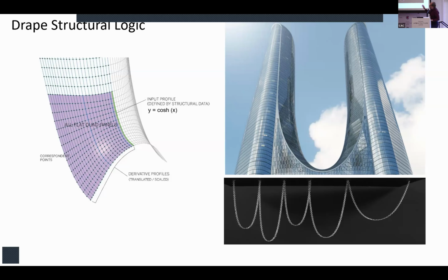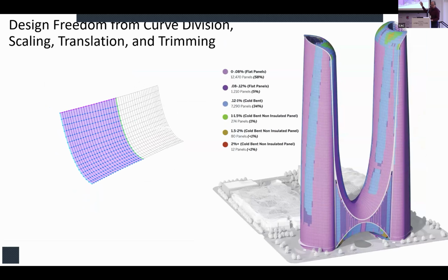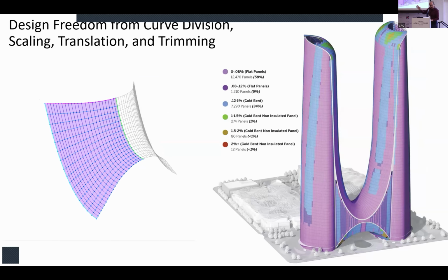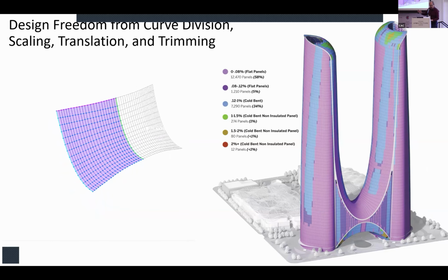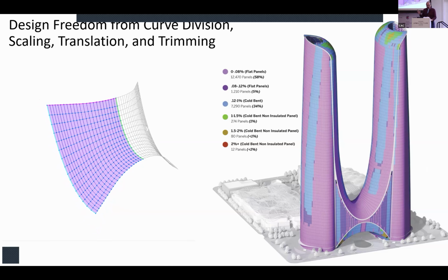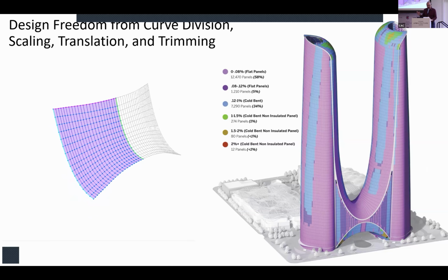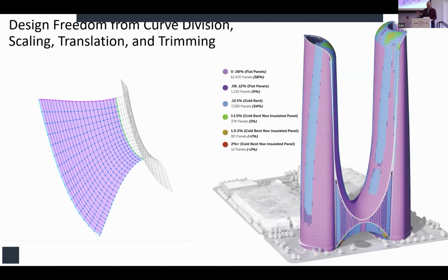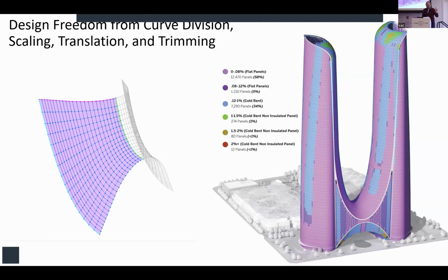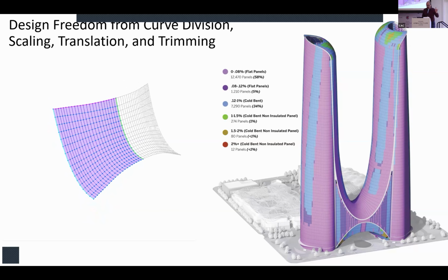What we needed to do on the engineering side was take that correct solution, a catenary, hanging steel sections, and scale it, translate it, trim it, right? So we got flat panels across this doubly curved surface. Those are all exactly flat panels, and a good looking architectural solution. That's something that engineers really need to take seriously, and that I try and advocate. But that is all within the sandbox of catenaries everywhere for gravity, flat panels everywhere for construction.